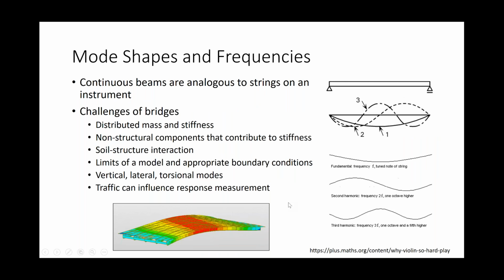So here's yet another look at this, maybe a little bit more physical, where you've got a fundamental mode operating at a lower frequency. Go to a higher mode of vibration. It's going to have a higher frequency, as you can see, and a higher mode still with 3 half waves. You've got a higher frequency still.